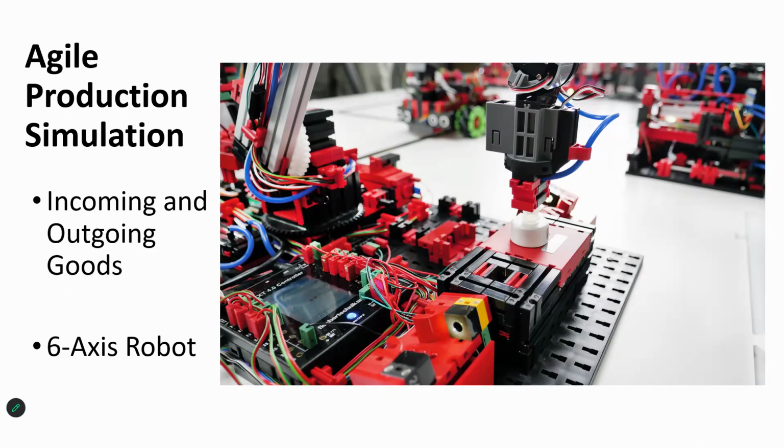So essentially what you'll have happen here is that raw materials get delivered at the goods receipt slot. They're positioned on the color sensor for quality control using the six-axis robotic arm with a vacuum gripper, and then they're encoded on the NFC reader. So basically what you'll see here, at the very bottom of your screen, is an electric eye setup. That is where the workpiece would be entered. It would be picked up by the robotic arm with the vacuum gripper and moved over to this station here, where the NFC chip is encoded, and then it's decided where it's going to move on to next.